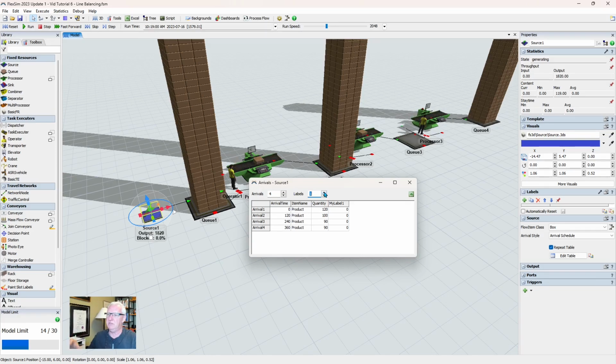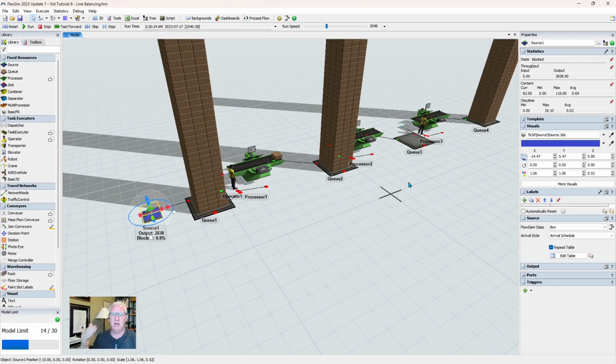or you want to identify different kinds of product to come in, you can have a product type, and say the first shipment is type 1, and then I've got type 2, then type 3, and then type 4 product coming in. Being able to attach a label to the material like this gives us some fun options on the way down. We can start applying some logic depending on the type, so we can control the setup time or the cycle time or the inspection time or which machine it goes to, all that sort of stuff based on the product label that comes through.